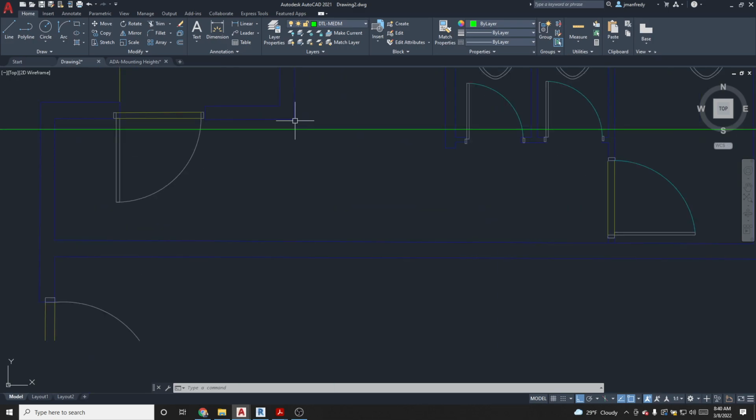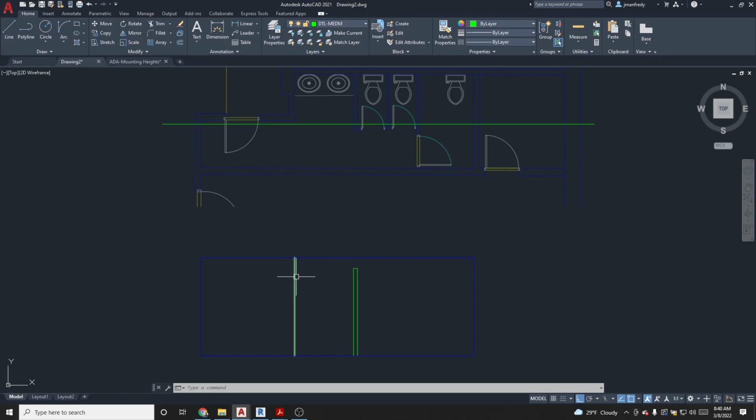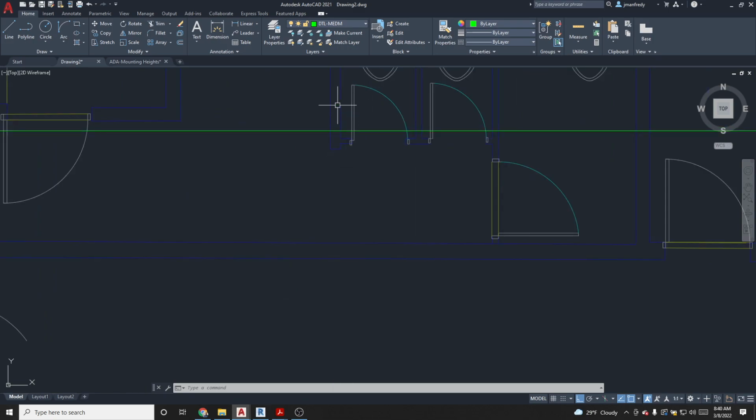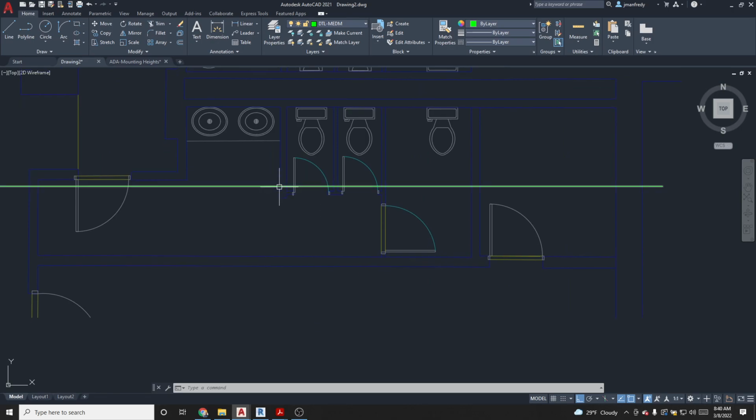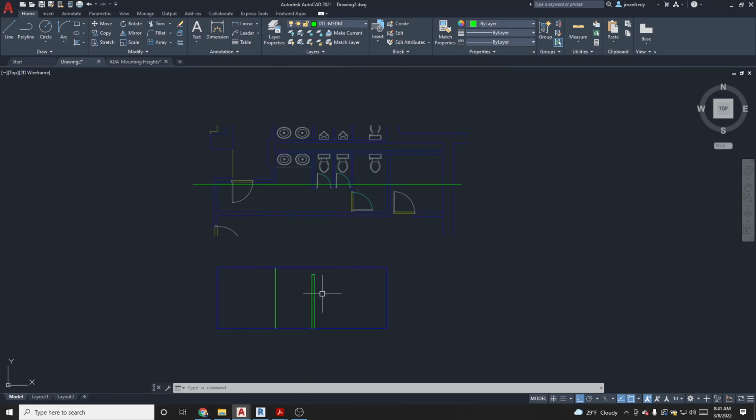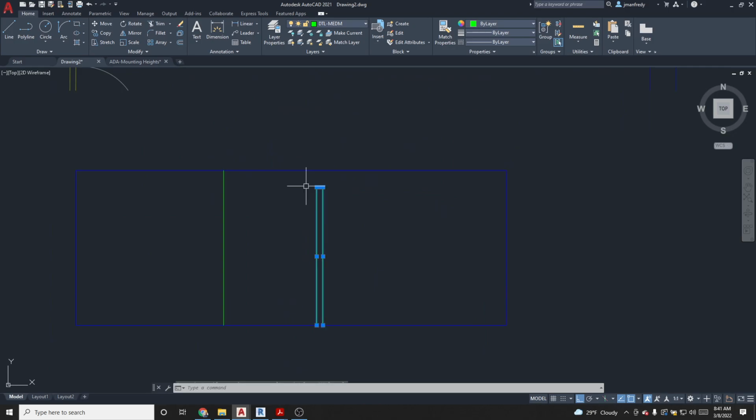So this wall is an elevation line, is detail medium. But this line here got cut by this imaginary line here. It's going right through the center of these laboratories and these stalls here. So because I'm cutting through them, I should draw this as detail bold.